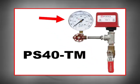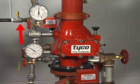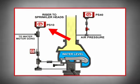To aid in testing the low pressure switch, Potter offers a pre-assembled PS40-2, a BVL, and a high-quality pressure gauge in the model PS40-TM. Dry pipe valves have an alarm port that may run to the outside of a building to operate a water motor gong. Under normal conditions, this section of piping has no pressure or water. This is where a Potter PS series pressure-type water flow switch is installed to monitor the system.